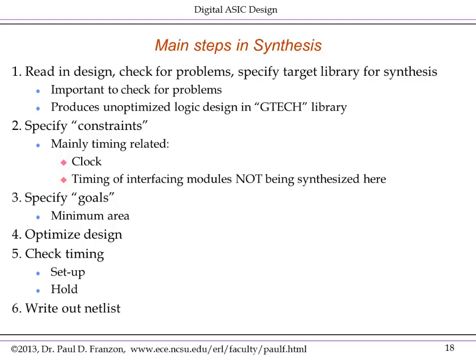What read actually does is map the design into a library, usually the generic GTECH library that is part of the tool. It is unoptimized at this point. It has not done any logic optimization. The next step is, in Synopsys terminology, to specify the constraints. These are mainly timing related. What is the clock? What are the delays on the interfaces in particular? Then in Synopsys terminology, you specify the goals, which usually is to minimize the area.